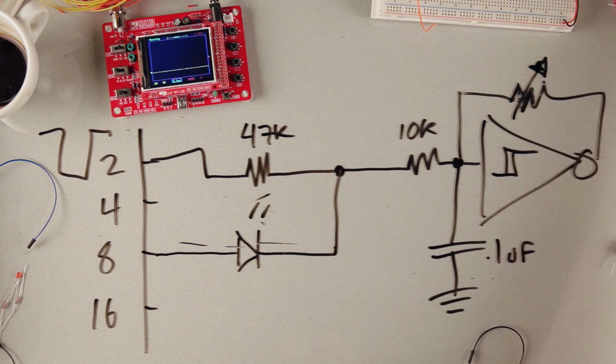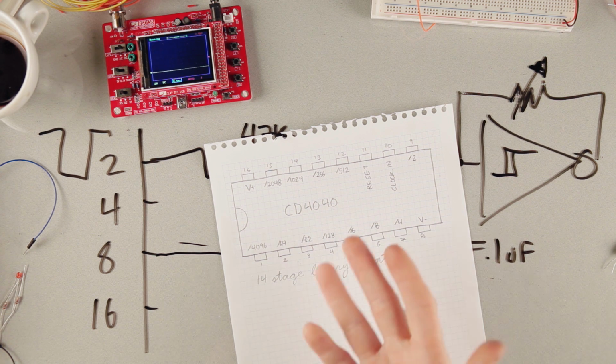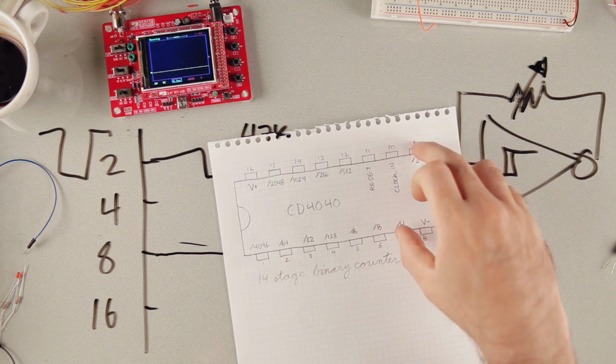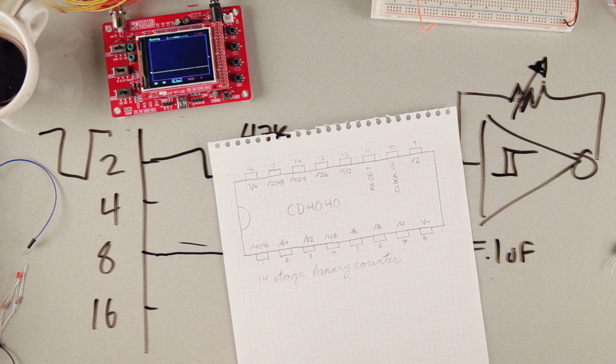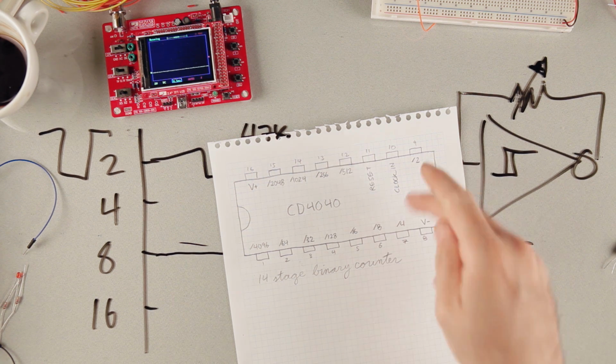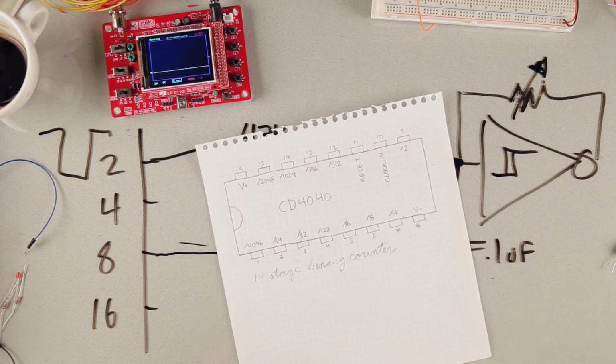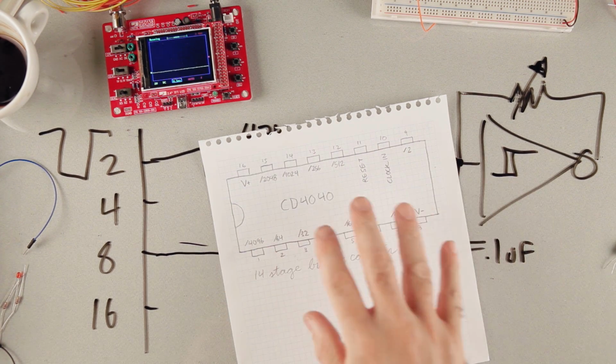So this chip, the 4040, is what I'm going to be using, or what I do use for lots and lots of projects, and for everything else I'm going to be talking about in this tutorial and the next, I'm going to be using this chip. So from here, I'm able to get all kinds of interesting combinations of rhythms. You can get sub-octaves. I use it for clock dividers. So maybe I have the divide by 4 clocking a drum machine, while the divide by 2 would be clocking a sequencer. So there's tons of uses for this.